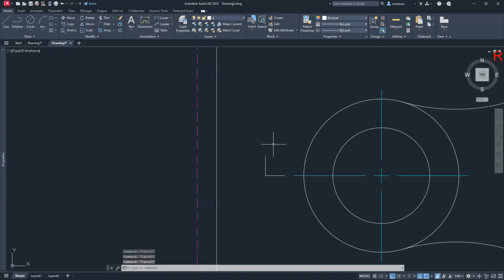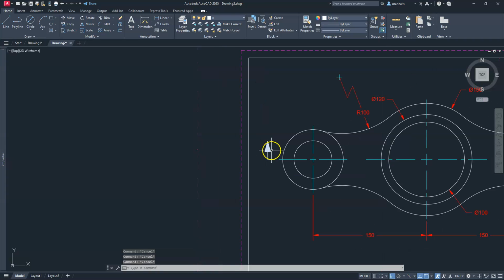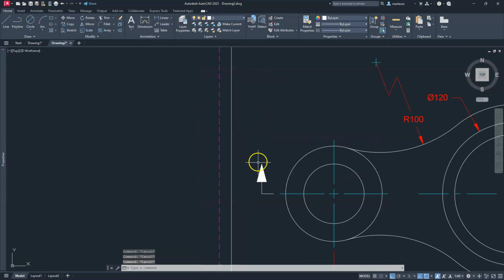Next, I'm going to go ahead and draw a quick arrowhead, and I'm going to use the polyline command again. So I'll just go to polyline. I'm going to click here as my starting one. And then I'm going to come down to the word width, right? So it says, give me a starting width. Let's go ahead and make that number 8. Give me an ending width. Let's make it 0. And now it just needs a height, right? So how far do I want to make this go up? Let's say 15. Looks good to me. Go ahead and hit escape, right? Let's go ahead and move this. And all I'm going to do is do this with the grip. So I'm going to select this arrowhead. I'll select this bottom grip, hit the space bar one time, and just place it onto that endpoint. Okay, so that's a quick arrowhead for us.